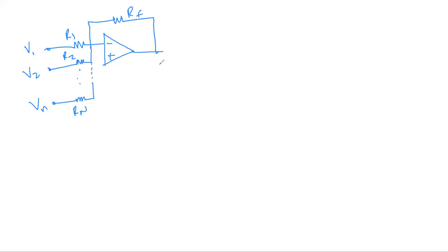Okay, and this is V0. What we said is that for an ideal op-amp circuit, when we try to analyze the system or get a model for this kind of electrical circuit, let's ground the positive terminal. All we need to start with is the feedback node equation. Here I have this node connected at 0. So I'm going to get 0 times the sum of all the elements' admittances attached to this node, which is going to be 0. So 1 over R1 plus 1 over Rn plus 1 over Rf times 0.